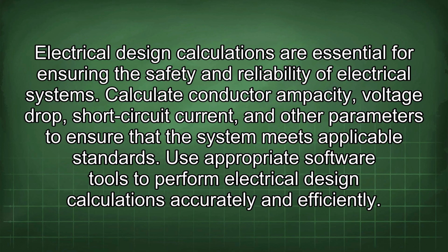Electrical design calculations are essential for ensuring the safety and reliability of electrical systems. Calculate conductor ampacity, voltage drop, short circuit current, and other parameters to ensure that the system meets applicable standards. Use appropriate software tools to perform electrical design calculations accurately and efficiently.